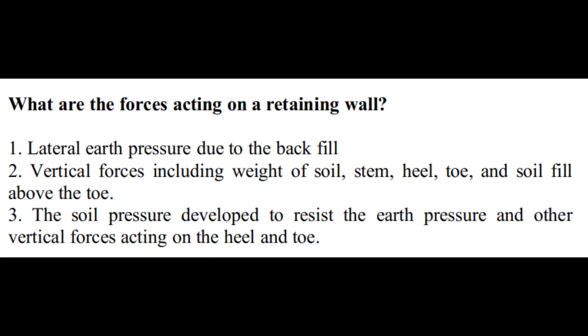Next question, very important from the structural point of view: what are the forces acting on a retaining wall? Number 1, lateral earth pressure due to the backfill. Number 2, vertical forces including the weight of the soil, stem, heel, toe and soil fill above the toe. Number 3, the soil pressure developed to resist the earth pressure and other vertical forces acting on the heel and toe.